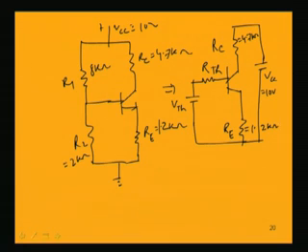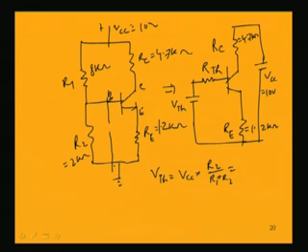So, now what is V Thevenin? That is equal to VCC into R2 by R1 plus R2. Here, we look from the base, this is collector, this is emitter. So, you look from base to ground, these 2 points, to the circuit on the left. I want to find out across these 2 points. So, VCC into R2 by R1 plus R2 is equal to 10 into R2, which is 2 kilo ohm, 2 by 2 plus 8, 10. So, the 10s cancel and it comes to 2 volt.